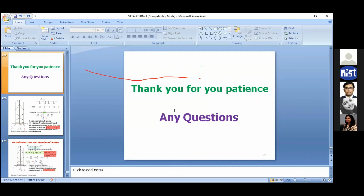Just one short question: is there any possibility that we can hybridize your quantum well structure, a parabolic quantum well structure, with an inverted quantum well structure? Yes, inverted quantum well. In one of our papers, we also made that inverted structure. In our research activity, we are only analyzing the mobility by modulating the structure.